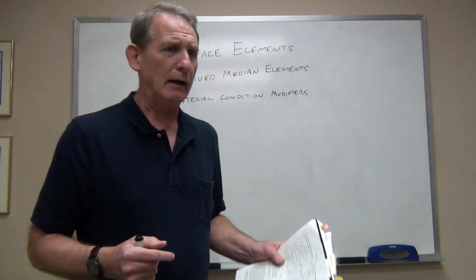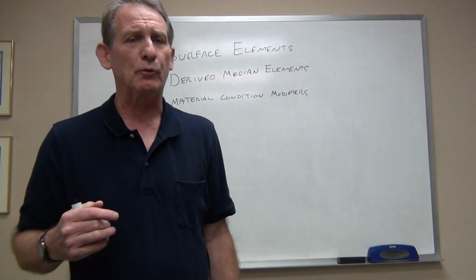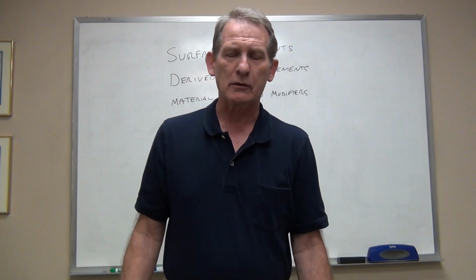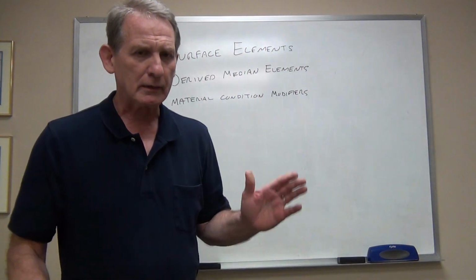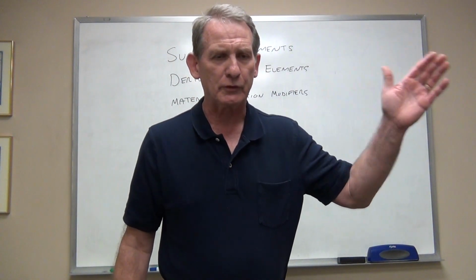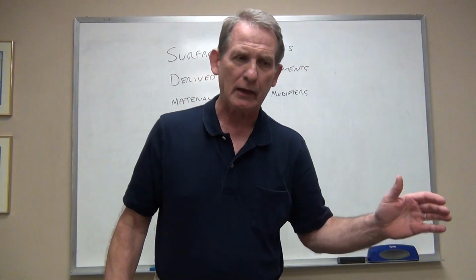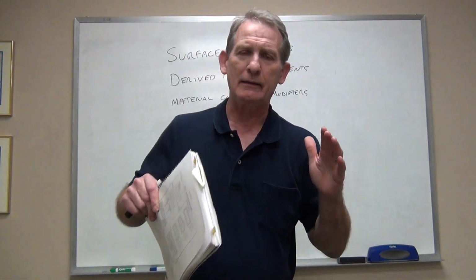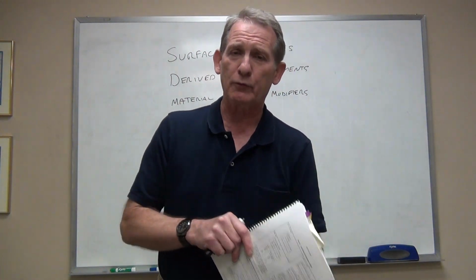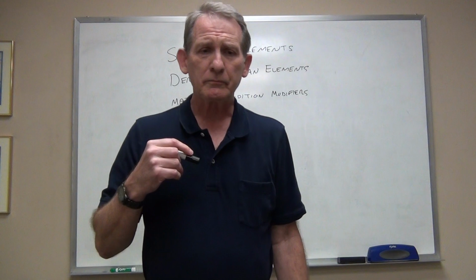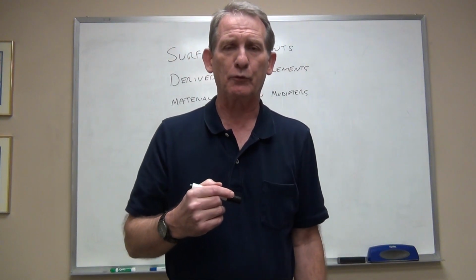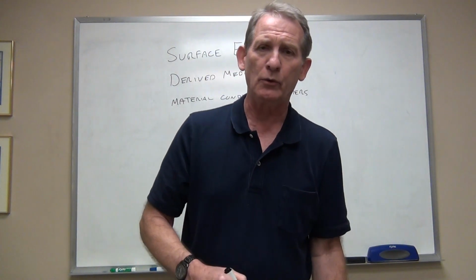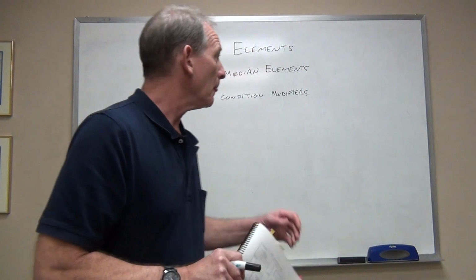You're going to see later on that we can also have derived elements that aren't linear. Derived planes are certainly common. So keep this distinction in mind of surface elements and derived median elements, and how you can tell whether you're controlling one or the other. Again, it is not as clear as it should be in Y14.5. You've got to look carefully at the feature control frame, where it is placed, and what information is inside of it. And if you review the video, that should refresh your memory about that.